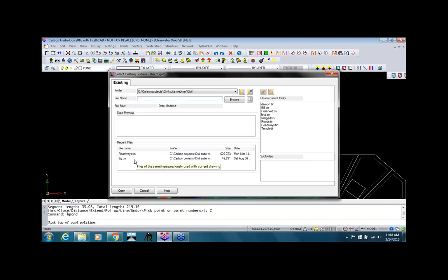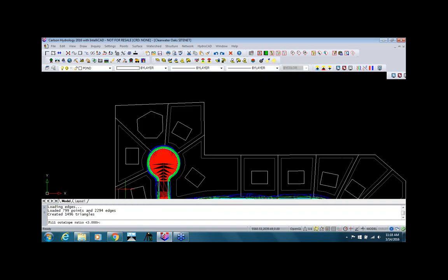It's going to also draw a 12-foot wide berm across the top that I can drive along. So I'm going to select my tin file, and my outfill slope ratio down here is at 3:1. I'm going to stick with 3:1 all the way across. And it's giving me a bottom. What it did is it sampled the elevations along that polyline, came up with an elevation of 264.86 at the lowest point on there. I can accept that, or I can override it.